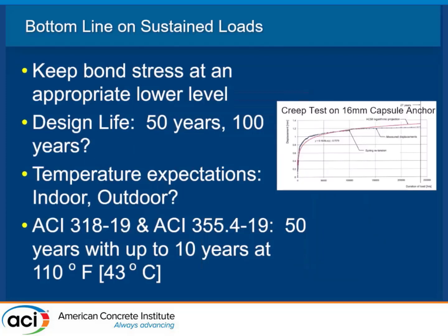And so, once again, per 355.4, the manufacturer is giving rules, information that they have to give you. One thing is sustained stresses or sustained loads, because we are using epoxy. Epoxy is what is keeping it in the concrete. And so they'll have information in there according to temperature and design life. And when you get the cut sheet, it'll tell you about that.